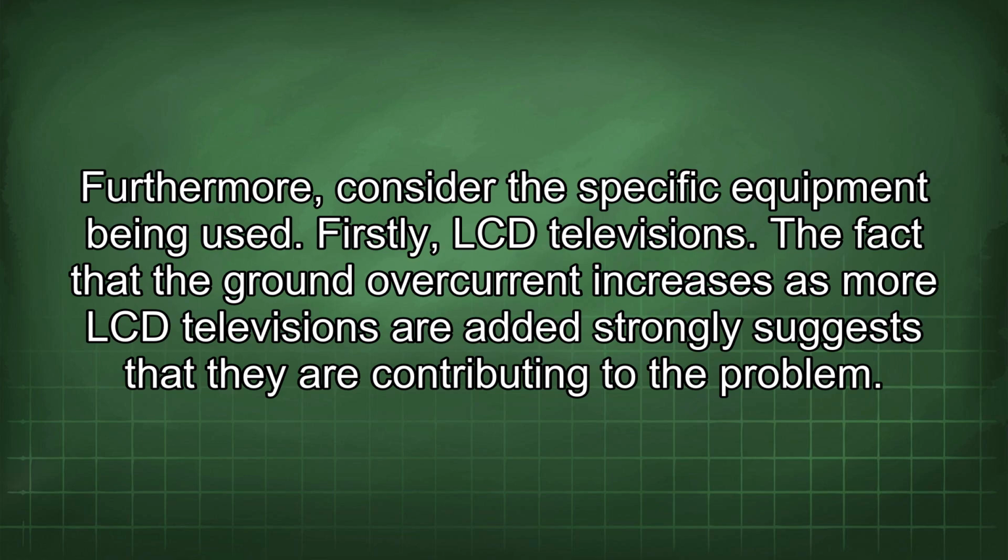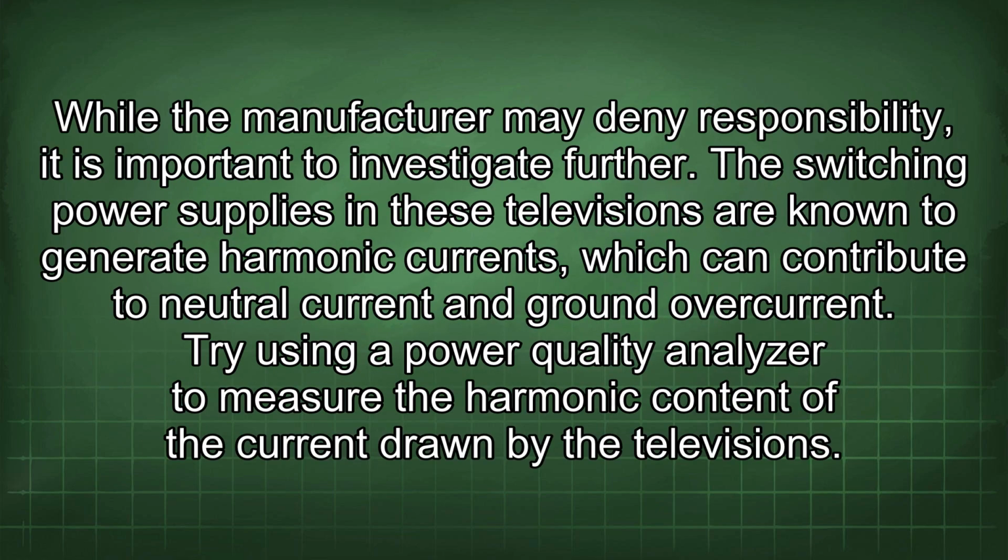Firstly, LCD televisions. The fact that the ground overcurrent increases as more LCD televisions are added strongly suggests that they are contributing to the problem. While the manufacturer may deny responsibility, it is important to investigate further. The switching power supplies in these televisions are known to generate harmonic currents which can contribute to neutral current and ground overcurrent. Try using a power quality analyzer to measure the harmonic content of the current drawn by the televisions.